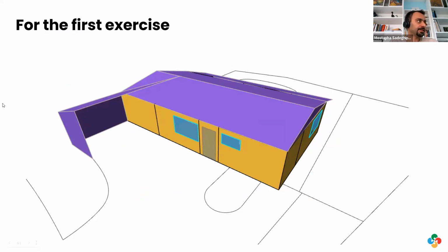So our first exercise is going to create this model. I'm going to use two different ways of doing it. The first one is I'm going to draw it over a plan, so you get a 2D model with some windows. And then for the second one, I will delete that and use the 3D geometry that we have. So this is what you do if you already have 3D geometry that's ready, and that's usually how you would prepare it for Ladybug Tools studies.